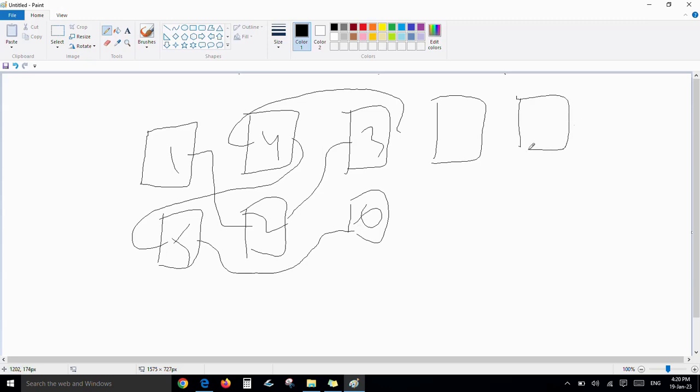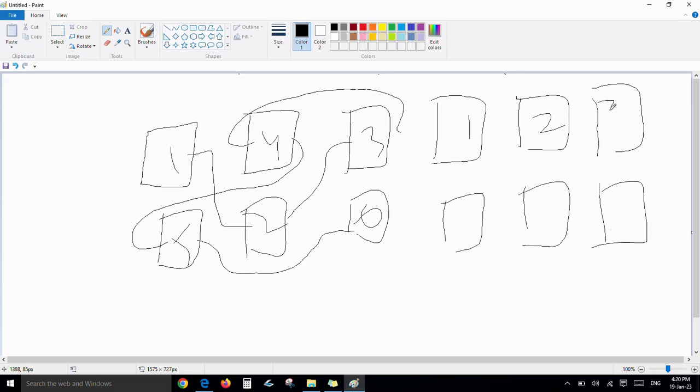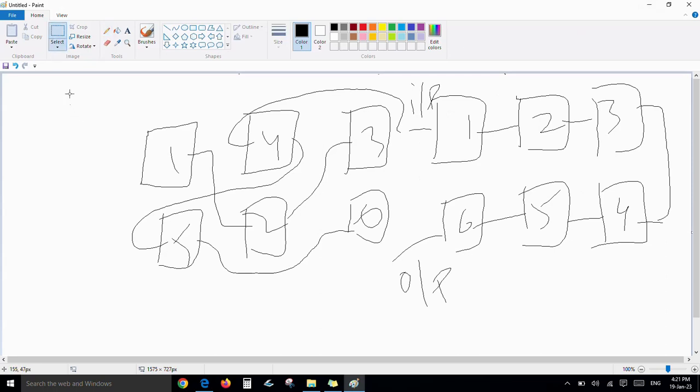After scan chain reordering, we reorder the scan chain in such a manner that if we give the input here, we get the output here, so it is not this clumsy. Actually, we are reducing the delay and routing congestion. Here the routing congestion is more, whereas here it is very less. That is the scan chain reordering.